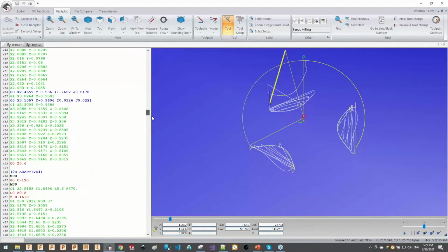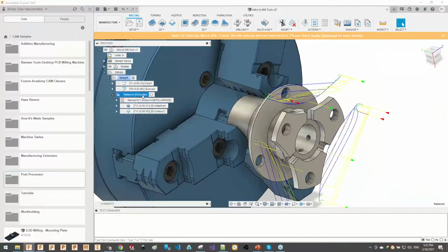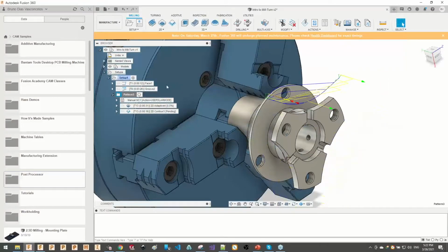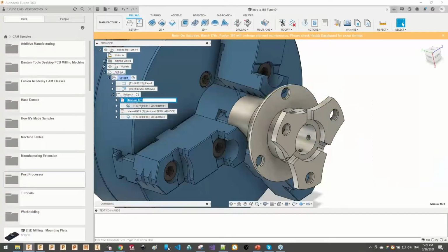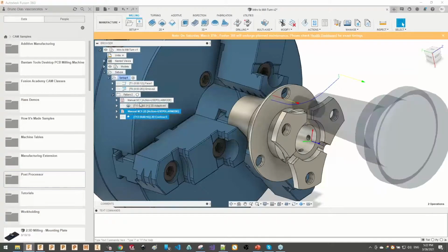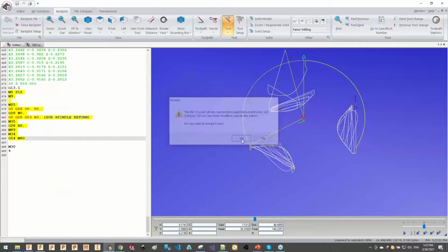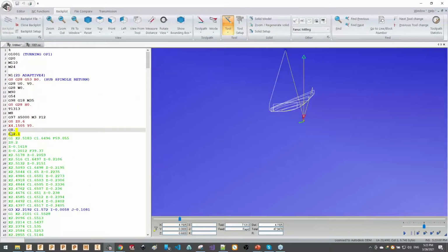All right. If you guys want to use the polar mode for the second operation that I created, just do this. Just create one. If we want to use the polar mode for the second operation, you need to duplicate that. You can duplicate that action and put it prior to that operation. So these actions that I'm showing you guys are valid per operation. So this is for this operation, and this is for this operation. All right. And there we go. So now both operations are using the polar interpolation.